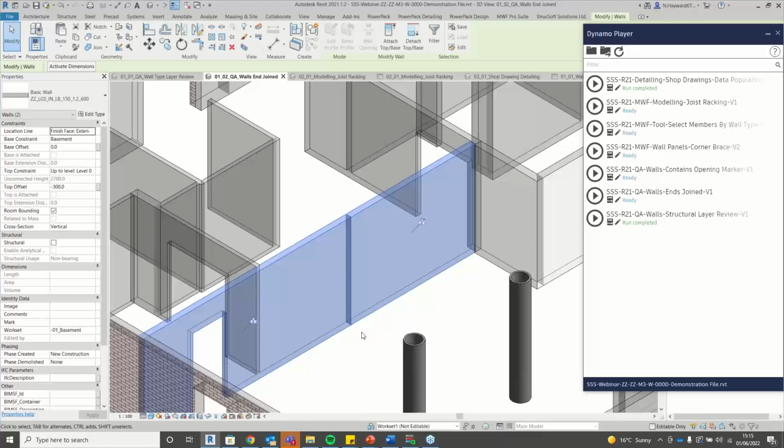Disallowing walls is a common practice for the most part, as users may wish to disallow certain walls to simplify their framing design. Other times, however, disallowed walls may come from either adopted architectural content or inexperienced and unintentional design decisions. It's that latter scenario that we want to address with a simple demonstration to help the user spot these areas and give some more clarity as to where those instances are within the project.